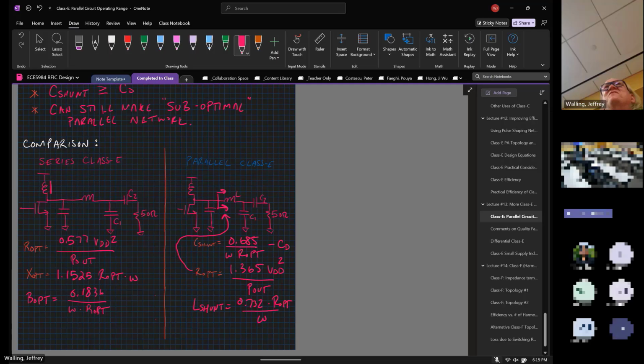It will, I promise. I'm modulating the switching resistance, because it's dependent upon the gate to source voltage. So the output power will depend on a second order effect, the switching resistance. I'm not going to see a linear change in the output power just by changing the amplitude drive.